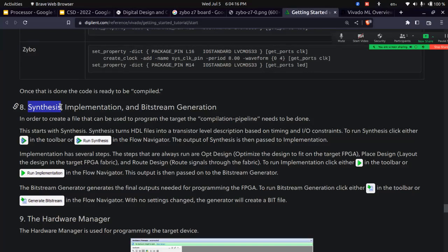We copy back, and after every loop, register 3 should have the Fibonacci numbers 1, 1, 2, 3, 5, 8. We saw all the signals and reads were fine before synthesis, and after synthesis it broke. The control unit broke.